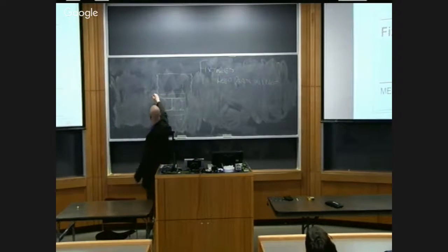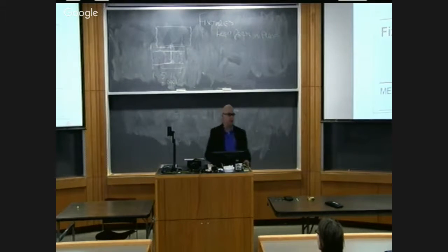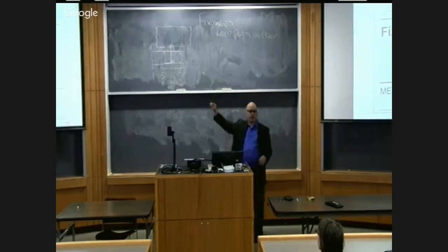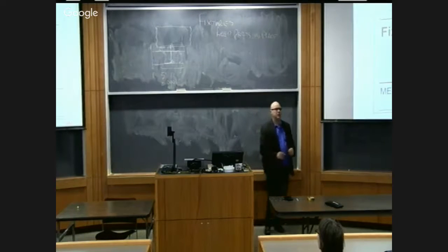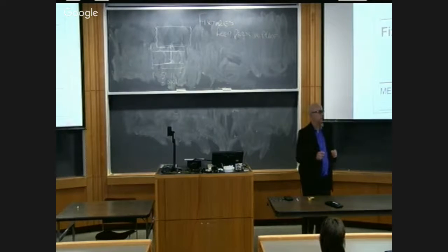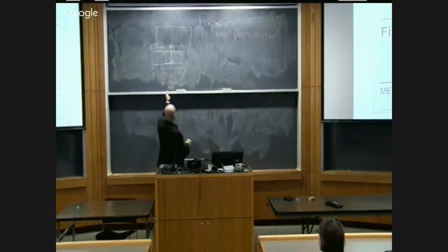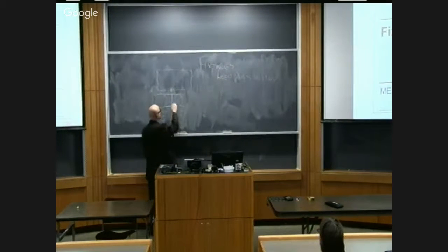And let's say my tolerance on this dimension, let's say this is 5 inches, plus or minus 0.001 inches. So I want that part to be 5 inches long, plus or minus 1/1000 of an inch. We've cut one end of it, so now that one end is square. Where should I put my work offset? So on the end that I already cut, since we did the other one in the center, we can put it in the center here.